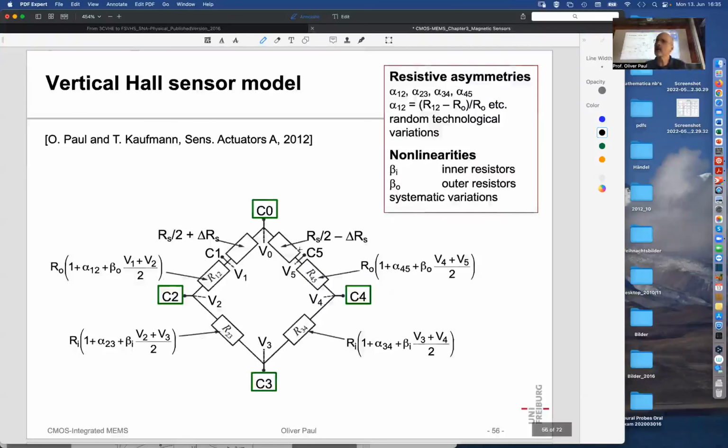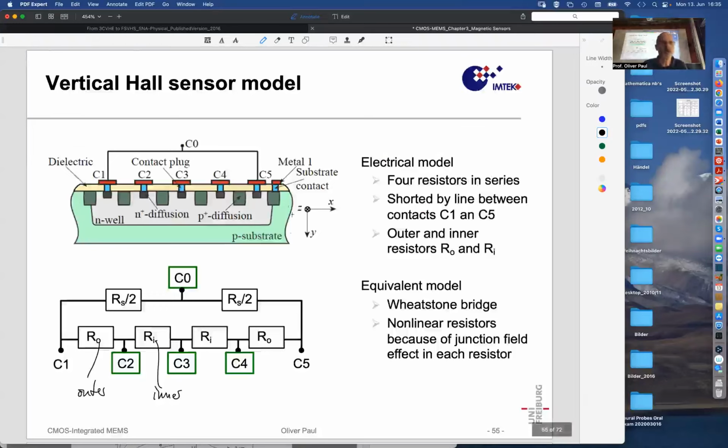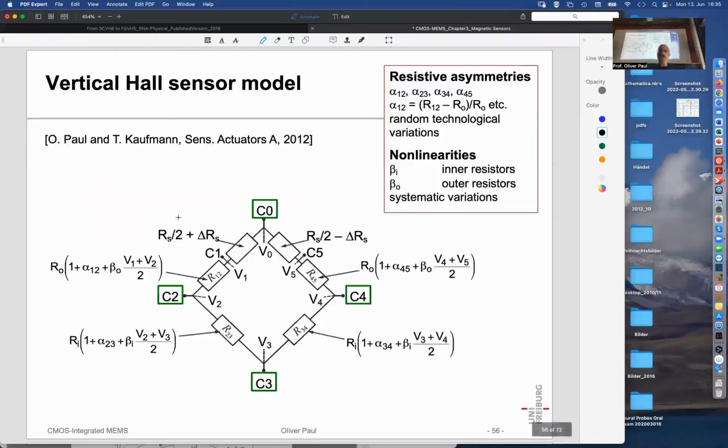Now, when you look at that, what do you call it? A Wheatstone bridge. Yeah, and it's a hard thing to look for ages at that structure and say we turned a plate into something linear, and then at the end to say, hey, this is still a Wheatstone bridge-like structure. The PhD student did not see it, and I only saw it once I drew the schematic, because then I was more flexible in my mind. And then suddenly I said, oh, this is a Wheatstone bridge. I can do an analysis.